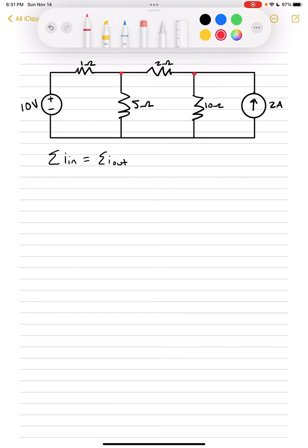So now I'm going to walk through the steps of nodal analysis and how we can find nodal voltages and things like that. The first thing we're going to do is choose a ground, and basically what that means is we're going to choose a reference area that we want the voltage to be 0 compared to the other points. So let's just put the ground right here for now. Again, I said this voltage equals 0 down here, which means that the voltage up here is going to be higher than the voltage down here because that's a 0.